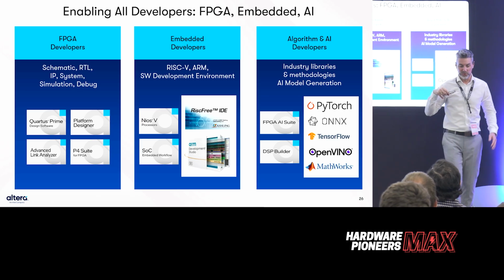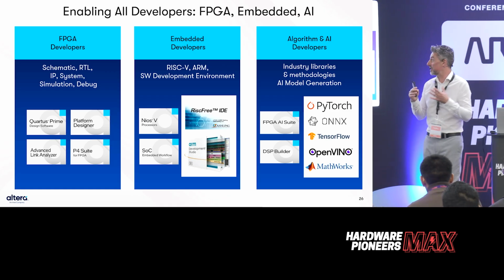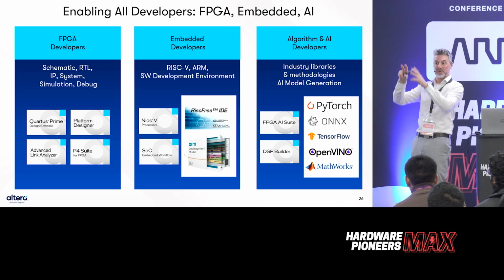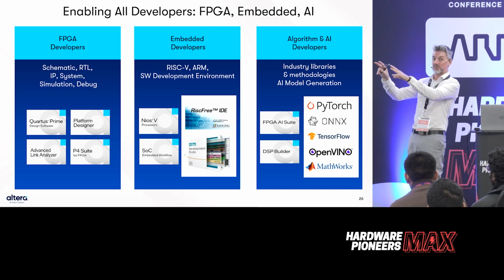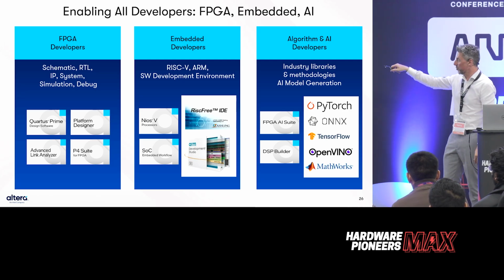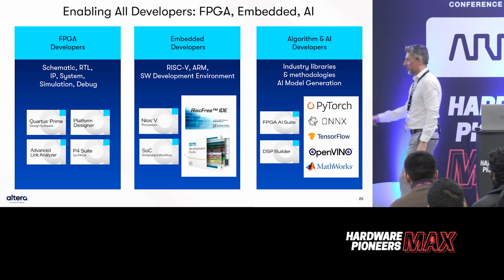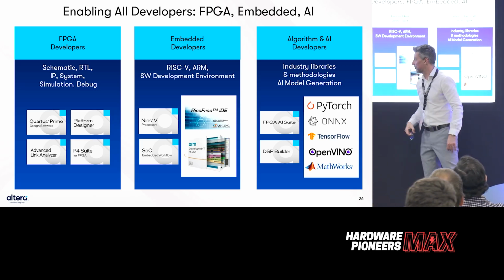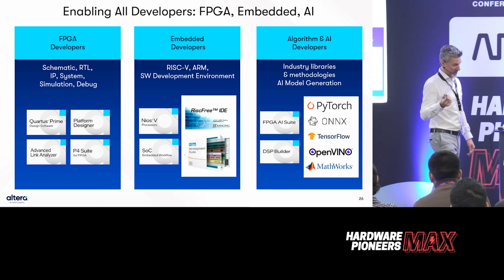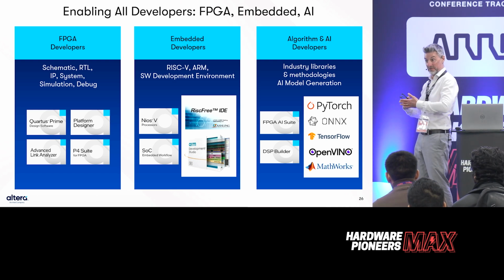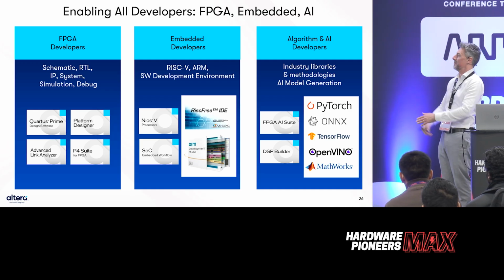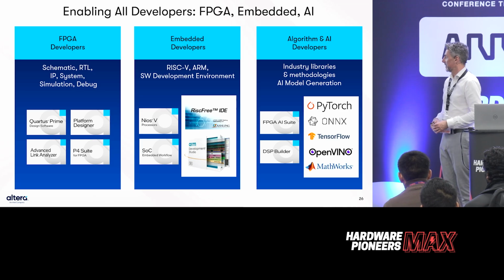We've got a high-level IP tool, so you can stitch together, say, a system with an ARM core in it. The high-level tool will say you can just drop these bits of IP in, like here's an ARM core, here's some memory, here's an interface to something else, and you can connect it up graphically and let the tool worry about the code underneath it all. So all the guys will have some form of high-level tool flow. And there's a bunch of debug tools as well, things like logic analyzers built into the tool that you can then get traces out of the fabric onto an external system, either streaming it or frame by frame. So there's lots of debug tools available.